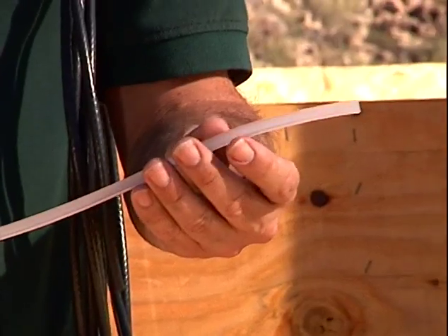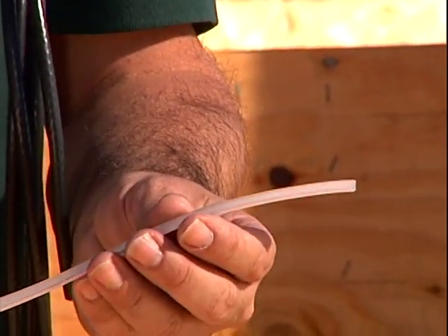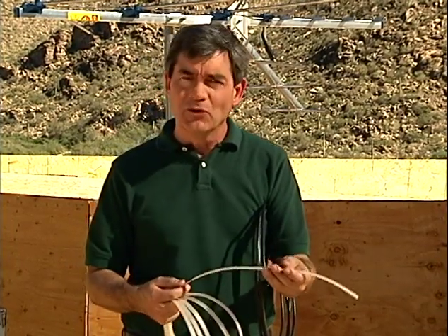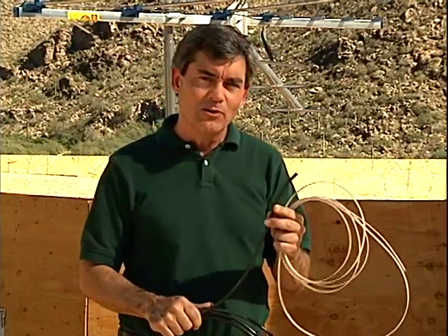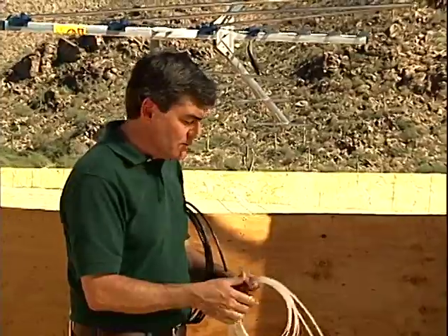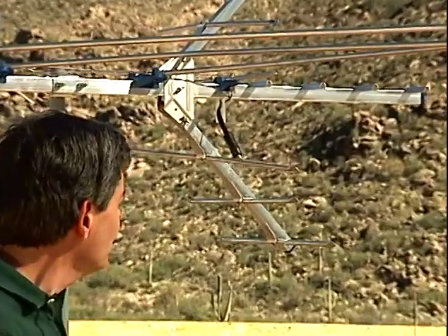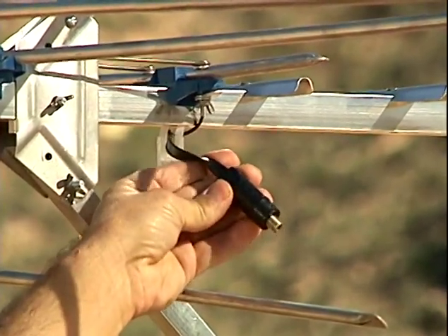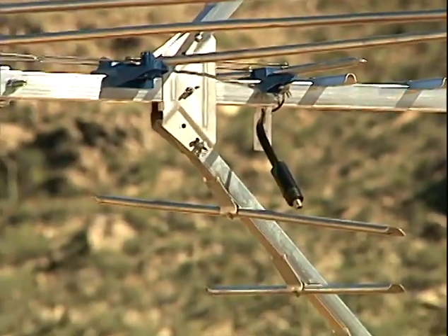Historically, off-air antennas are designed to use this older twin-lead cable. Despite its appearance, it's actually a very good low-loss cable. The trouble is you've got to keep it away from metal objects and other cables, and it's susceptible to noise pickup. A better choice is to use RG6 coax. Now, the characteristic impedance of RG6 is 75 ohms, while antennas are designed to use the 300 ohm impedance of twin lead. Therefore, in order to connect coax to the antenna, you'll need to install a 300 ohm to 75 ohm impedance transformer such as this balun. Now, we're going to cover more about the selection and installation of off-air antennas in part 2 of the course.